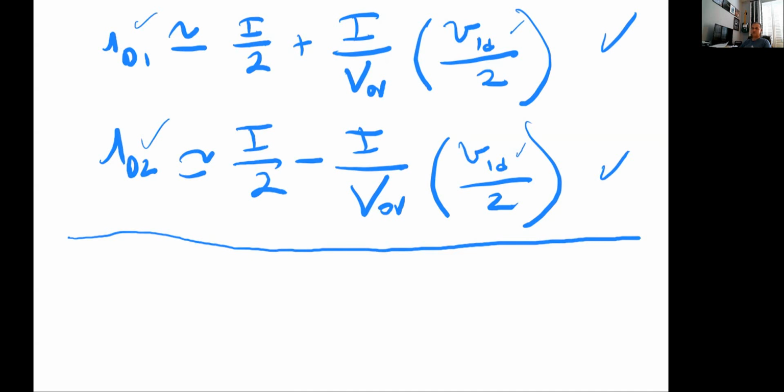And since you have been working with op amps at a macro level, using it as a device, you do know that if you want to be in the linear region, you want the differential inputs at the positive and negative inputs of the op amp to be very close. That's when the op amp is linear. And that's where the virtual short characteristic of the op amp from a model perspective comes in. So all this starts working together.